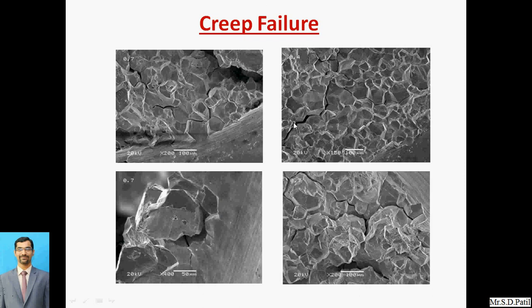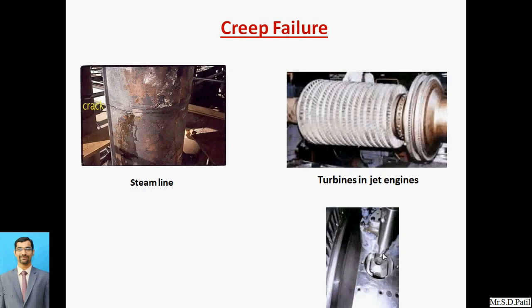So these are the creep failures, showing how creep failure occurs. But this kind of failure is not there in the tensile test, where the component simply breaks and we need not study it under any microscope. In the case of creep, these internal cracks are formed under high temperature. These are practical images of how the crack has been formed and how the failure has occurred.